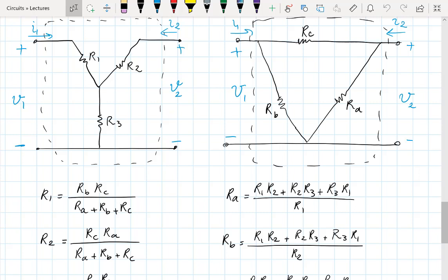And by the way, this is a good example also that being in series is not just a matter of what the drawing looks like, right? So again, if I'm not connecting R2 to anything up there, the current I2 is 0. And so R1 and R3 would, in that case, be in series effectively. So from the left, I'd see R1 plus R3. Similarly, if I don't connect anything to the left, and I look from the right-hand side, I'd see R2 plus R3.